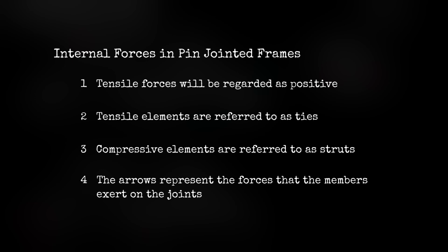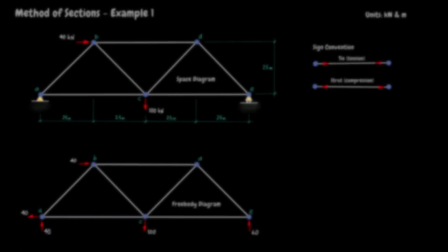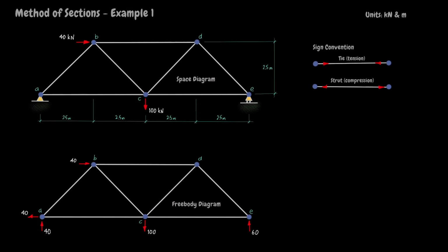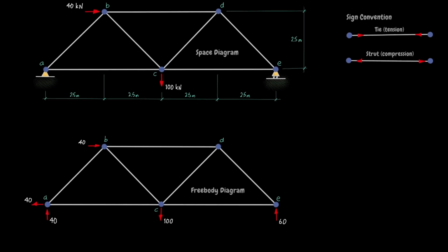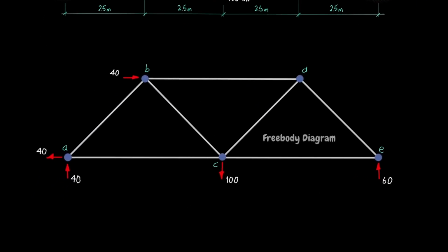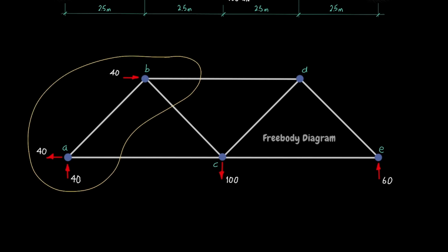Applying the method of sections works by cutting the frame to expose up to 3 unknown member forces. The term section implies using a straight line to cut the frame. That's fine, but Dr. Jim encourages you to use free body diagram bubbles to achieve the same effect. There are many sections that will expose 3 unknown internal forces. Our first section will expose the force in members AC, BC and BD. Draw a free body diagram bubble that cuts these 3 members.